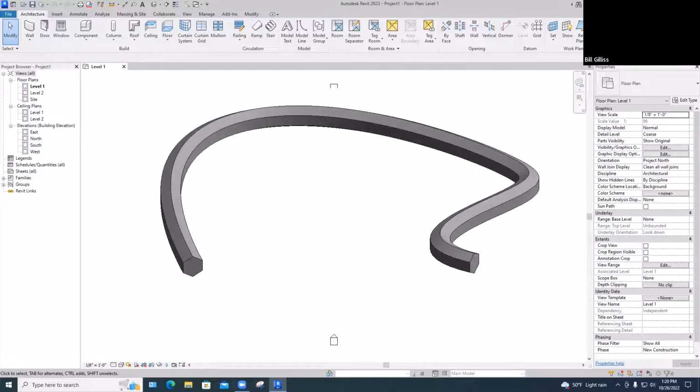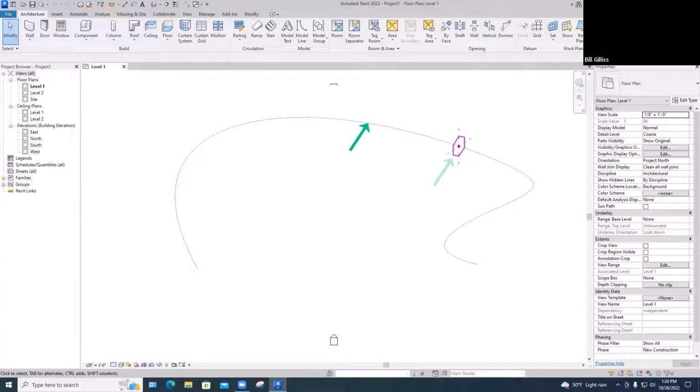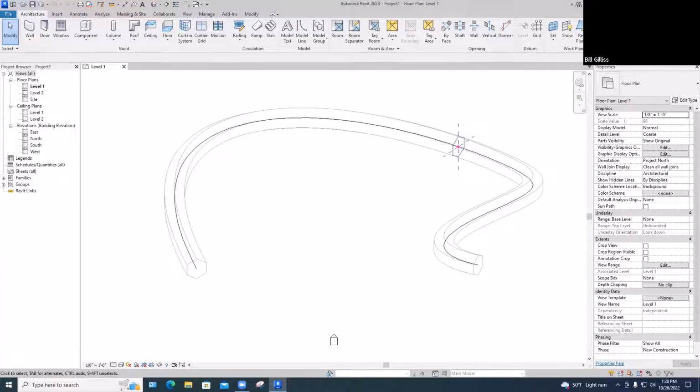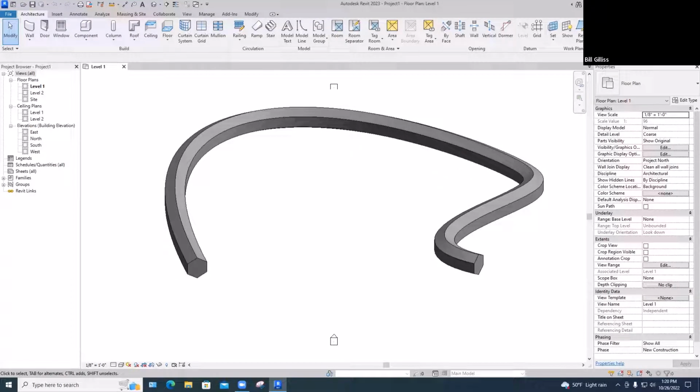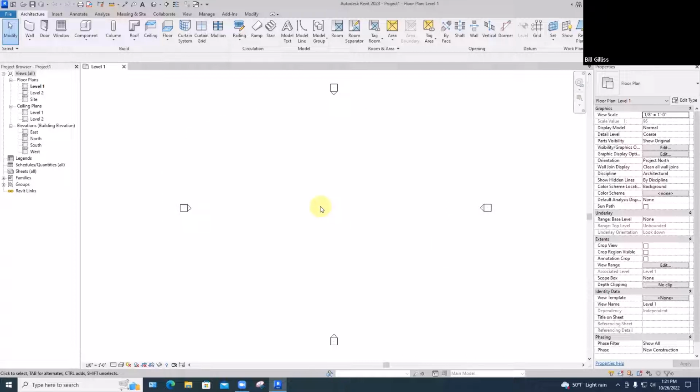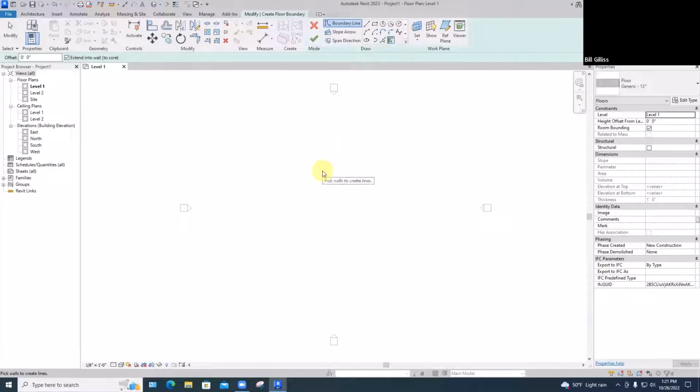And lastly, in Revit, every three-dimensional object is based upon one or more two-dimensional objects that we then manipulate or add or subtract from. So if you can't make 2D things accurately, 2D shapes, you can't make 3D ones at all. This applies to abstract shapes as well as to regular building components like a floor. And whenever we're starting to create some three-dimensional object, we always get our 2D drawing tools here. And I just want to click and make a rectangular floor and then say OK.